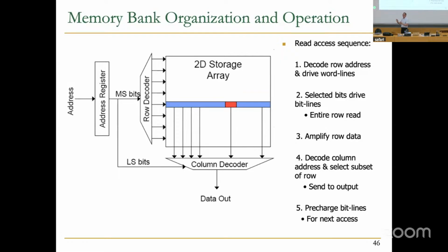So DRAM or SRAM, they both operate this way. You've seen how DRAM operates exactly. We're not going to go into SRAM in detail. SRAM is a little bit easier, actually, except when you go into extremely small technology nodes. When you go into small technology nodes, all of the charge levels are also small, so you get noise issues, etc. But we're not going to go into those issues right now. But still, the operational principles are the same. That's the beauty of memory. They all look like this in the end.